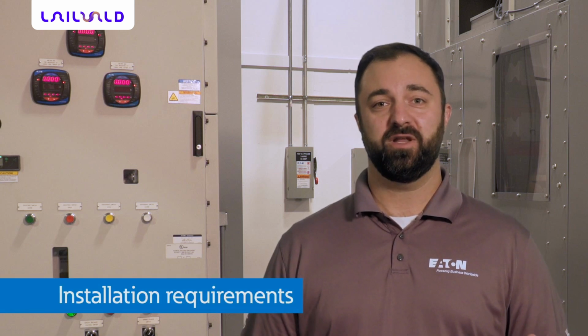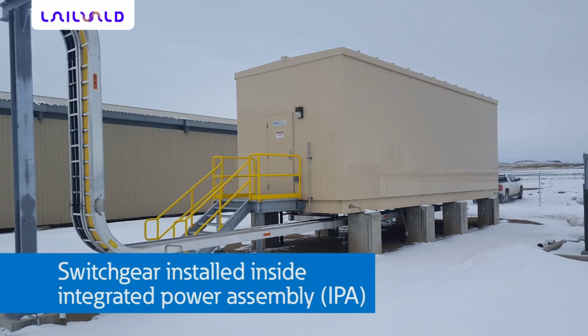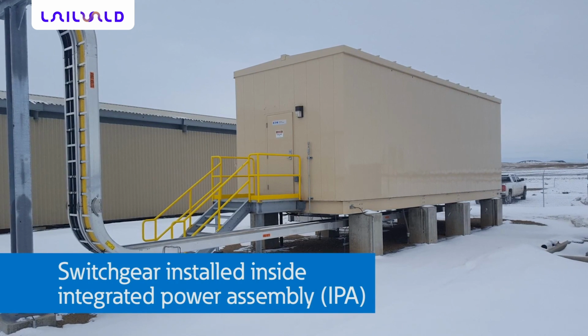We have discussed footprint and control power requirements. Now let's look further into installation requirements. Medium voltage AIS switchgear can have incoming voltage brought via cables or bus duct in the top, bottom, or side of the assembly. Whether your installation is in an integrated power assembly, over a cable vault, or installed on a concrete slab, an AIS lineup provides you with flexibility in your design.